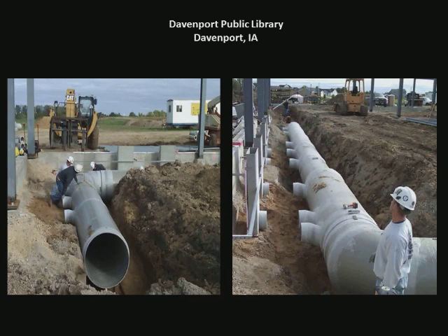One of the issues with insulating the boot is these are going to come all the way to the top. The standard on this is probably about 3/16, maybe a 1/4 inch thick. When you go to put your register grill at the top, if I have something that's 3/16 that I have to cover, that's not a big deal. But if I start getting into double wall, now I've got 2 layers of 1/4 inch fiberglass, and I've got a 1-inch insulation. This is a 1.5-inch rim all the way around.